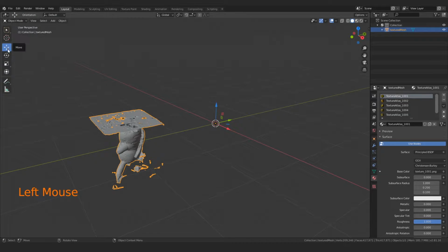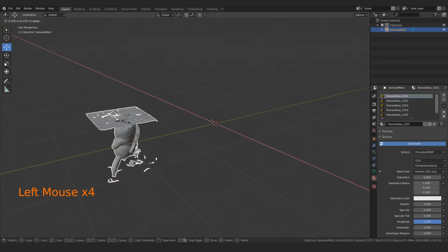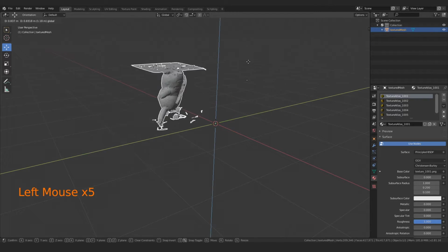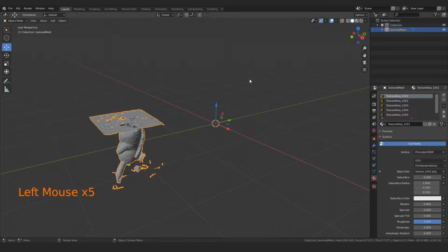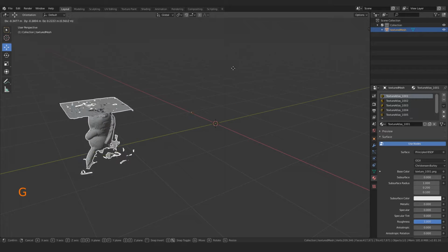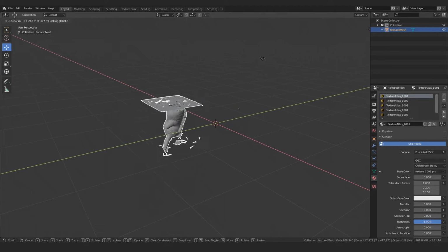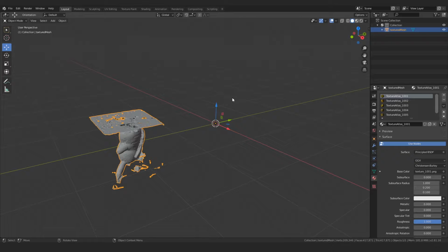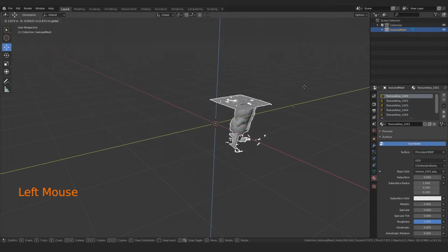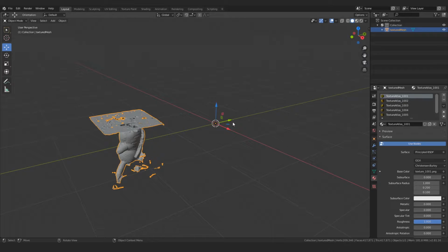You have movement, so if I click that, we get a little gizmo that allows us to move. And again, it works in the same fashion. The nice thing about this is it has some intermediate ones, so you can lock on 2 axes. The way that you would do that is you would activate this, and then you'd hit shift in whatever axis you don't want it to move on using the hotkeys. Again, that becomes second nature. I don't really move on 2 axes, but this can sometimes be useful depending on what you're doing. It's up to you. So with movement, we have the ability to constrain by 2 axes.